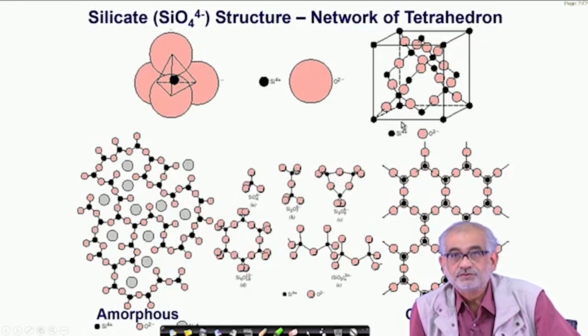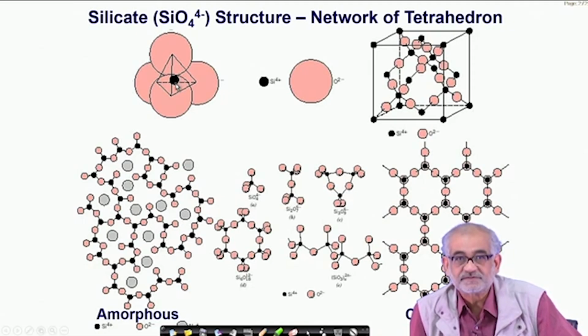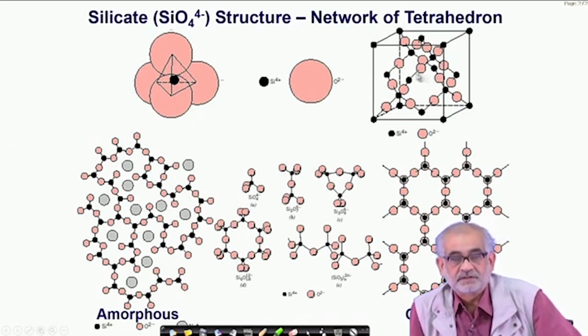Now we are moving into non-crystallinity. So, for example, imagine that we have a silicate tetrahedra, simply a tetrahedron where I have a smaller species in the middle and 4 bigger around. If this is a single unit, I can pack this unit in 2 possible ways. I can pack them in such a way that the center, this dark one, coincides with one of these dark spots shown here in this particular cubic lattice, cubic unit cell, such that the other ones automatically follow a certain trend, and in the process the whole structure will manifest itself as a crystalline aggregate.